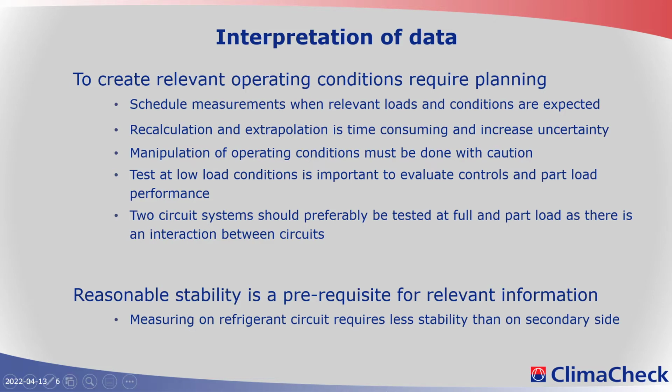It's of course attractive to go to sites and do maintenance checks when there is nothing else to do. So not when there is a reasonable load, but the measurement is not going to be very good. So again, that's of course the big advantage with having continuous monitoring. Then you just go in and pick out relevant data points. But otherwise try to measure at reasonable stability at as high load as possible.